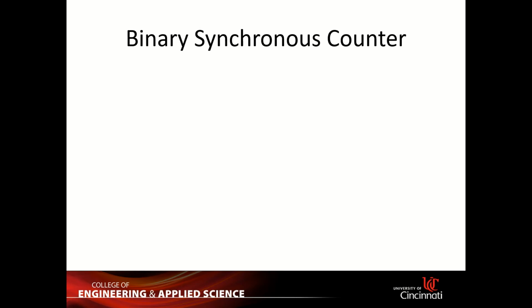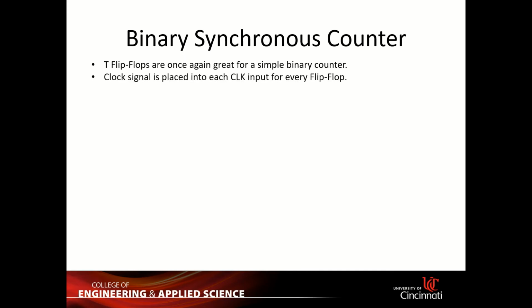Okay, so let's go through one example. T flip-flop is pretty common when you make a counter, because the key function of T flip-flop is to flip the value. So when you count something in binary, you actually notice that the bit just flips. It either goes from 0 to 1 or 1 to 0. That's the key of counting. You can have the clock placed into each clock input of every single flip-flop. And you can have